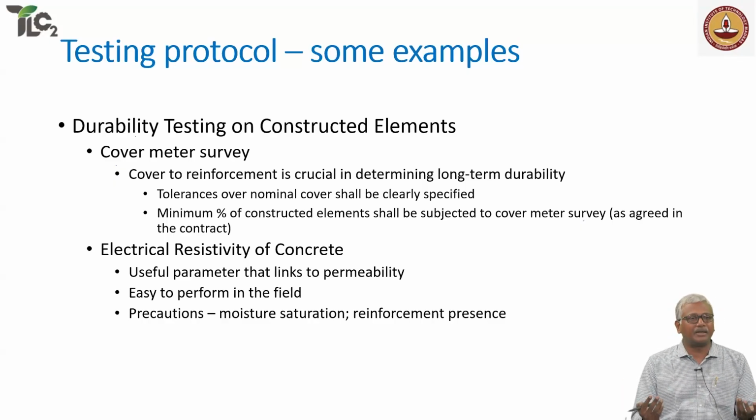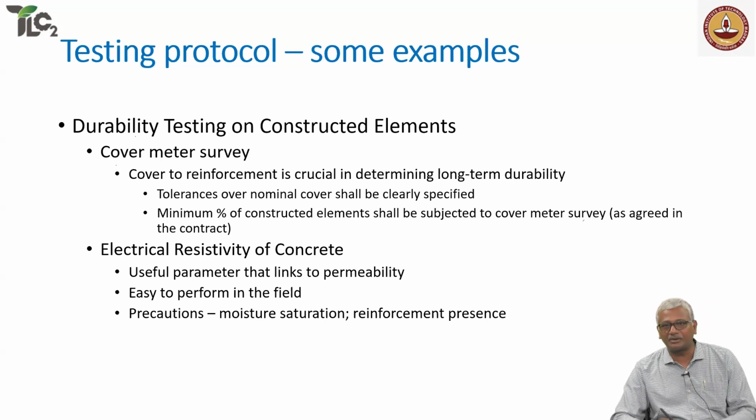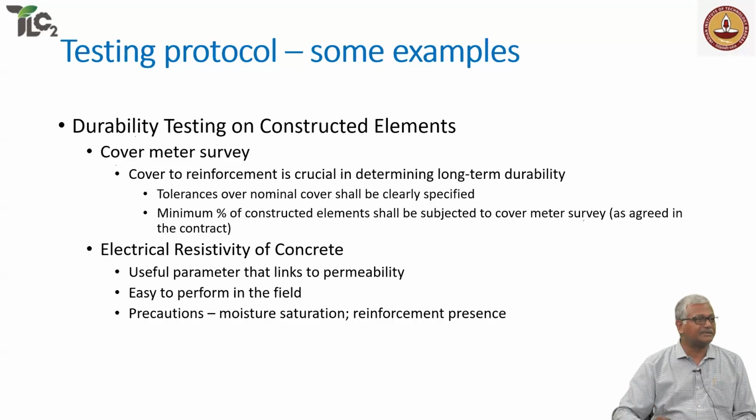It can't keep on thinking about what can happen here, what can happen there, how do I include this, how do I include that. That's not possible in a code. A code has to be simple, easy to understand. If you look at the code carefully, in several segments it clearly says it's at the discretion of the engineer on site. Code doesn't say that you have to restrict your fly ash content to 50%. Engineer can decide if he has data, right, that 70% fly ash is able to give you the required performance. Why not use it? It's reducing the cost of your concrete.